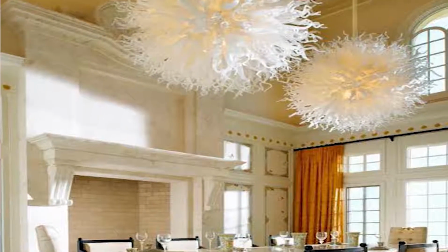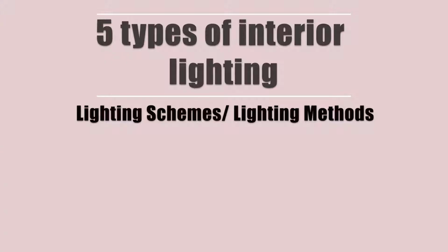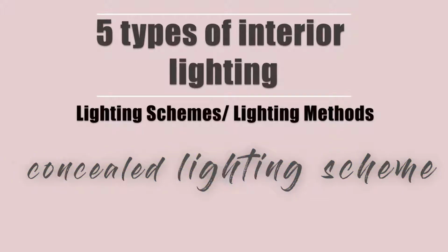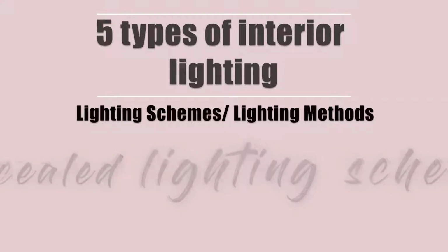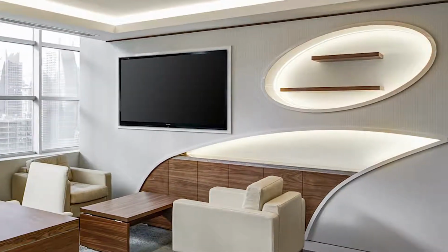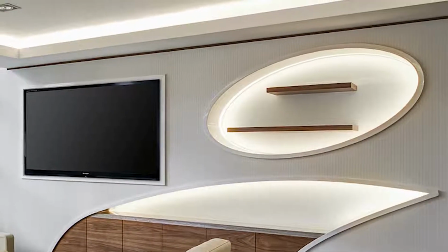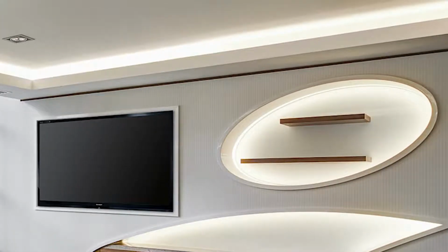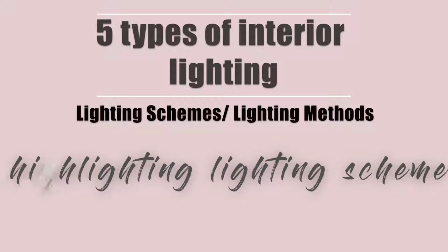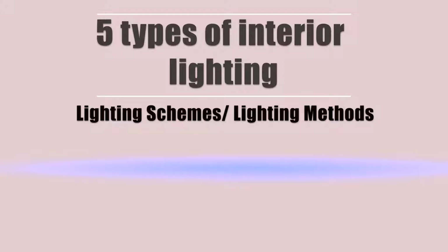The 3 other lighting schemes, though they are all subsets of the above mentioned, are the concealed lighting, which is also known as architectural lighting, where the fixtures are concealed. It can be any of the earlier mentioned, but illumination is produced such that the covering or protecting body is assumed to be the luminaire. The second is the highlighting or projecting lighting scheme, where a luminaire is directed to a specific surface. The third is underwater lighting, using diffusion or general lighting scheme models.